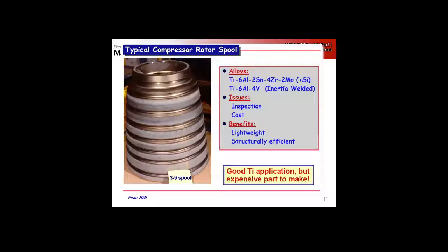But basically, you take two tubes, put them together with some force, right, and then spin one, right? So you have a mix of initially some frictional heating, but then lots of heating that comes from the plastic work that's being done, right? And then as you compress forward, the softened material flows out, and then you have a solid state metallurgical bond, right? So the key thing with inertial welding is you're not actually melting, right? So you don't have a lot of the problems that comes with traditional fusion welding.